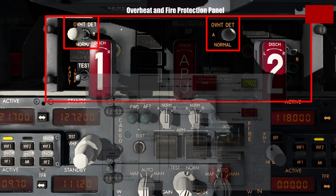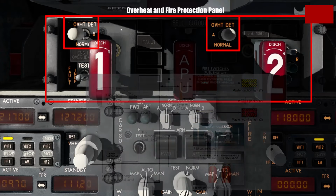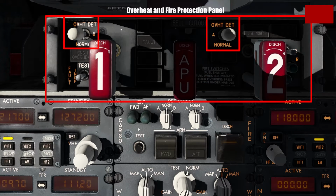This aircraft has two dedicated fire detection loops, A and B, which work independently of each other. In the real aircraft, pilots will be able to switch these loops for both sides to either A or B. However, this switch is not simulated on the Boeing 737 ZIBO mod and is hence always left in the both position. Moving below the switch, on the left side we have this test switch.